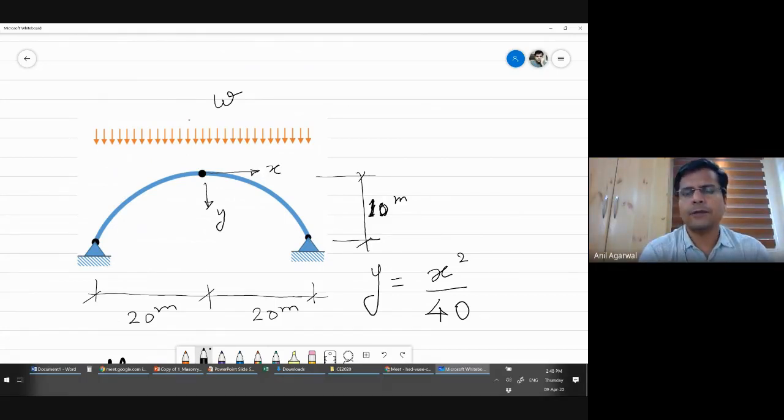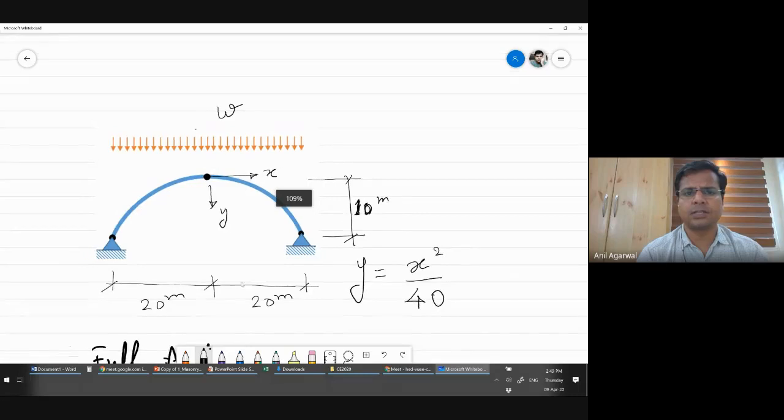If you don't use that hinge in the middle, you can still use the arch. The only issue is that then this structure would be indeterminate, and analysis will be slightly more involved. It can still be used as long as you don't introduce any inbuilt stresses. In order to keep it relatively simple, I have not left the dimensions abstract. I have actually fixed the dimensions.